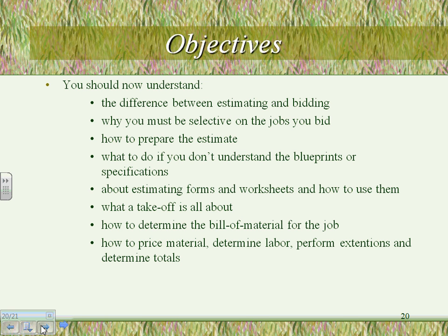Then on page 60, guys, they put the pricing and labor. They added all this equipment. What does C mean? Remember yesterday when you take off, C is 100. What does M mean when we do takeoff? 1,000. What does E mean? Each. Every time you see, for example, receptacle, insulated ground, 20 amp, 120 volt, E next to it, it's $11. E means each. So if I have 2 of them, each one of them is $11. When you do extension, what does it mean? $22 for both of them. Labor, the same thing, guys. The unit for the labor is C. C means 100. Okay? Then you go to page 61.